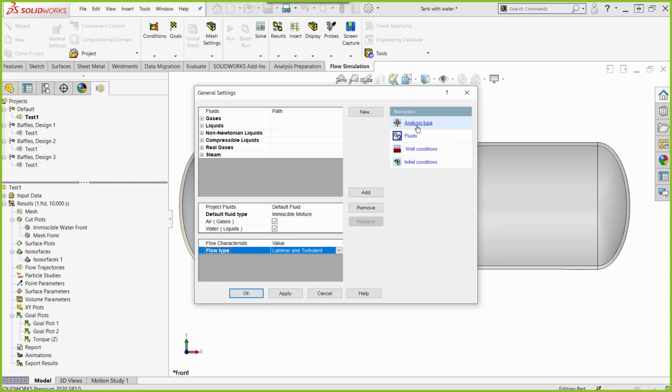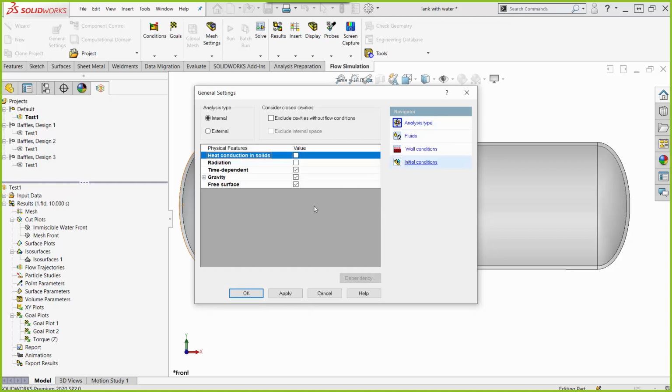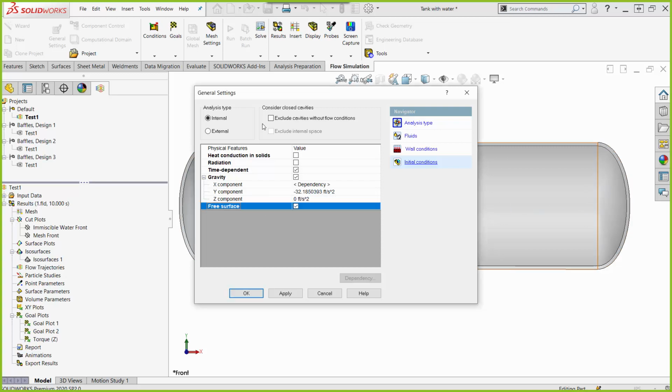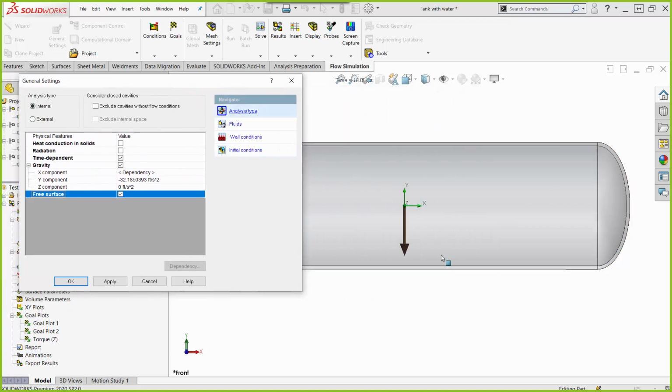The interface is called a free surface. That's a name used by SOLIDWORKS and generally to refer to the fluid interaction, that layer in between. And it's also what Flow Simulation uses to refer to the calculation method. You see that here. Also, the tank is considered to be positioned horizontally like this, where the center of the Earth is in the negative y direction. So we see that 1g loading there.